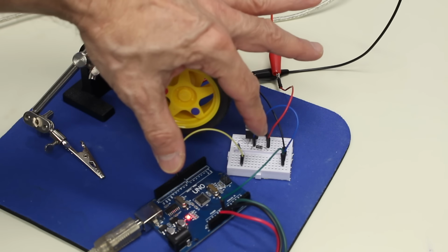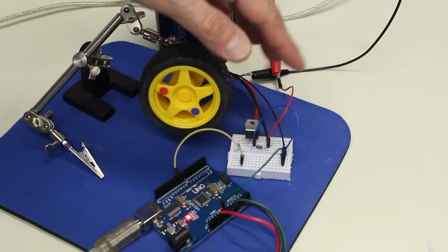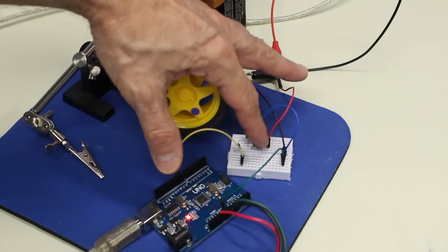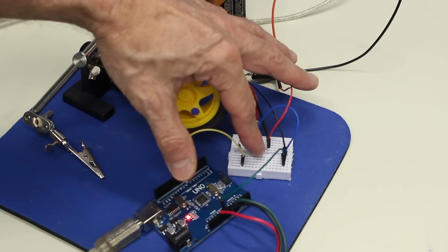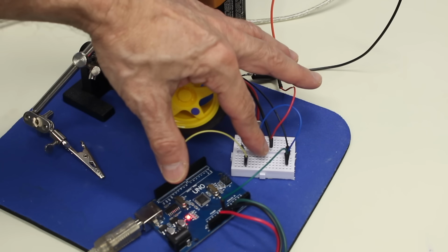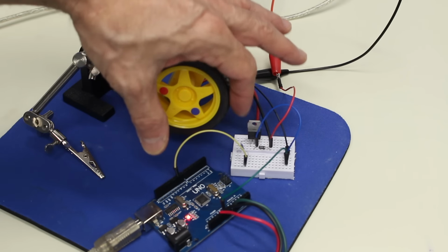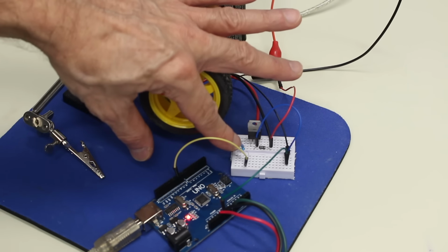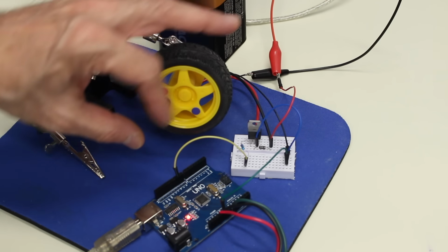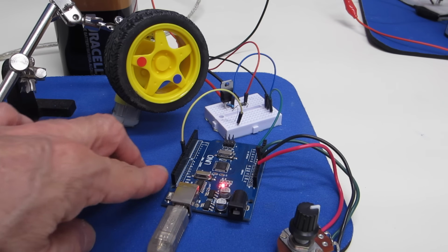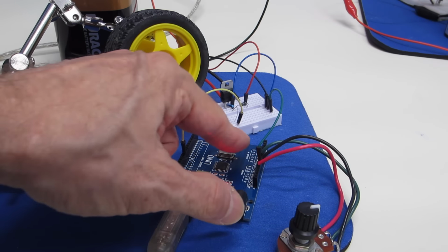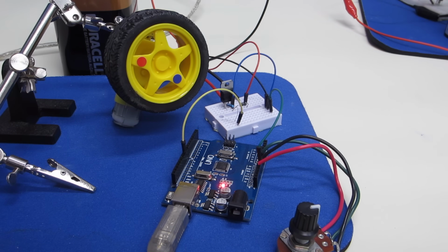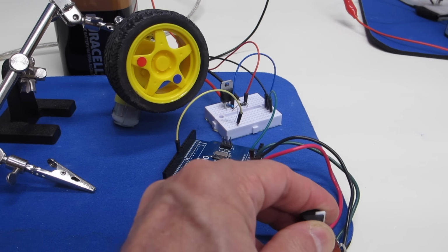Now, that may seem backwards to you, but that's actually the reason it's there. It's to take any of the reverse voltage that comes off of this motor when the motor spins and to absorb it. And so that's why the diode seems to be connected backwards here. But you have to get the polarity of that correct. If you don't get that correct, that's going to get very, very hot very quickly. Otherwise, the resistor over here, my current limiting resistor, and then of course the line out to pin 9 of my Arduino, and you saw the potentiometer, it's just connected to the ground and 5 volts in the Arduino and to the analog A0 input. So a pretty simple circuit and a very simple sketch, and let's just watch it work.